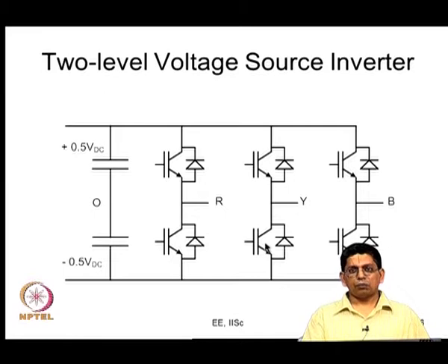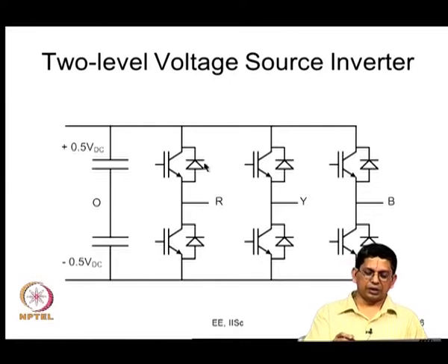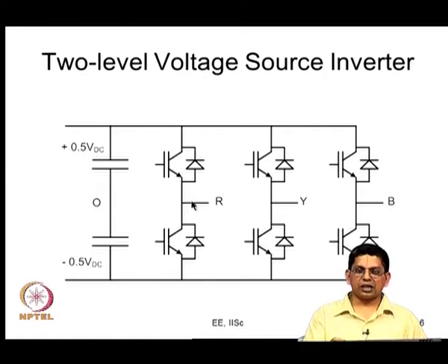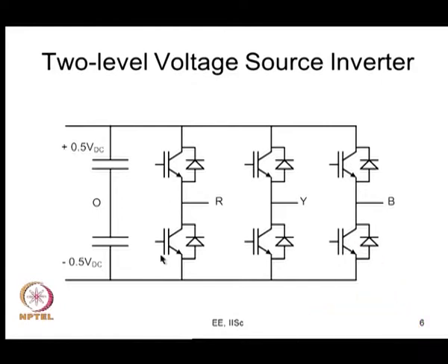So, now we are talking of the dead time effect in a voltage source inverter. First, a quick look at the voltage source inverter. Three different legs, single pole double throw switch. The switches are supposed to be switching in a complementary fashion, and that is where we have a difficulty now. The gating signals for the top and the bottom cannot exactly be complementary. The rising edges of both of them have to be delayed. The outgoing device has to be switched off first, and the incoming device has to be switched on next. This actually means the rising edges of the gating signals have all got to be delayed by time Td.